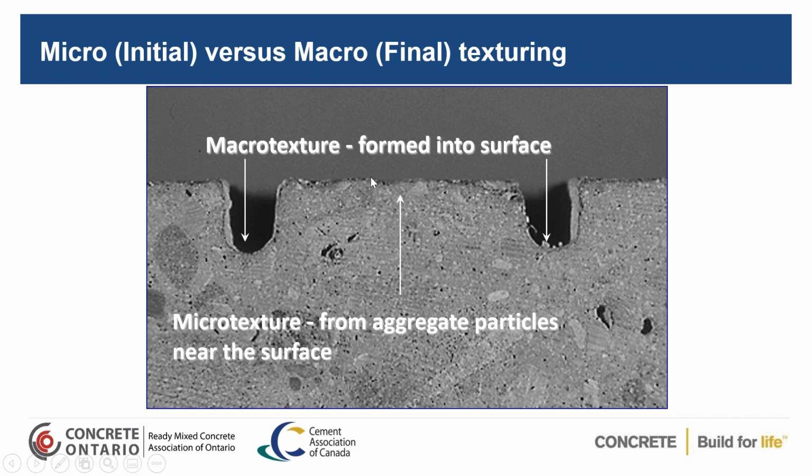The micro texture is the top surface here. This is when you have the burlap drag that roughens up the surface, and also where you have your paste and your fines. And the manufactured sand gives you the best skid resistance because it gives you more angular material.